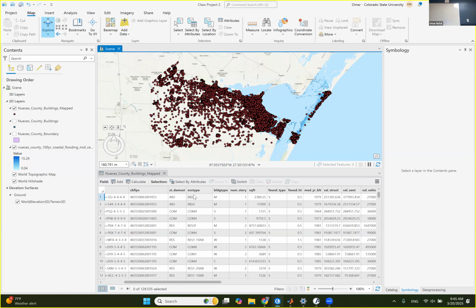It tells you how much loss this building is going to have if it is exposed to a flood of 2 meters. It tells you it's going to lose 20% or 30%. It is not a fragility that can tell you the exceedance probability of a specific damage state, okay? So we want to migrate, or shift, from these 33 to our 15 building archetypes.